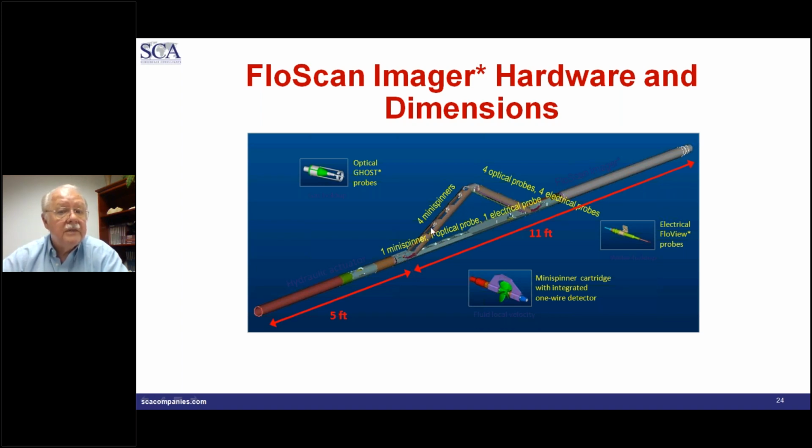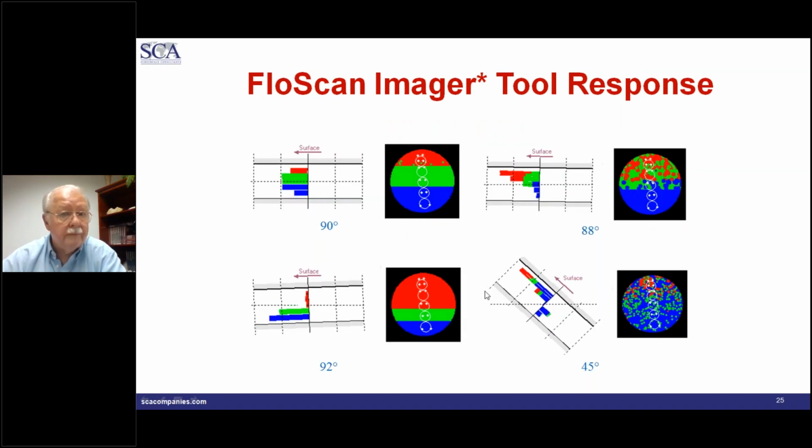These give you the velocity through 1, 2, 3, 4, 5 sectors across the wellbore. So you're seeing the same sectoring that we had seen before. On this figure, I have an array of 5 little circles. Each of those circles represents the position of one of the 5 spinners. And here are the velocities as indicated by those spinners. Actually, this is a measurement of the revolutions per second, which can then be converted to a velocity. Schlumberger has calibration curves for these spinners. So here we have 5 different velocities across the wellbore.